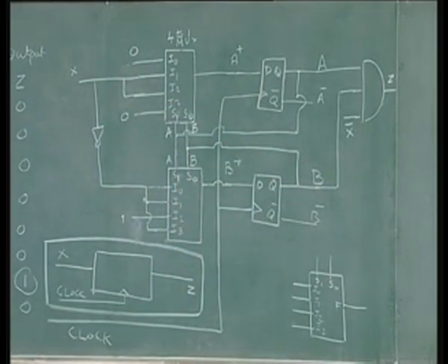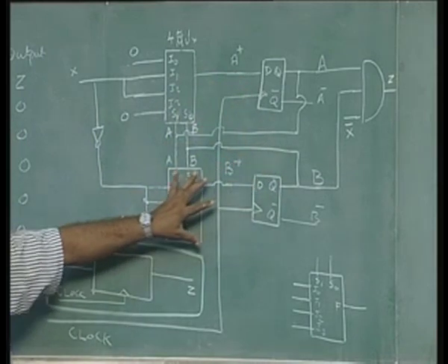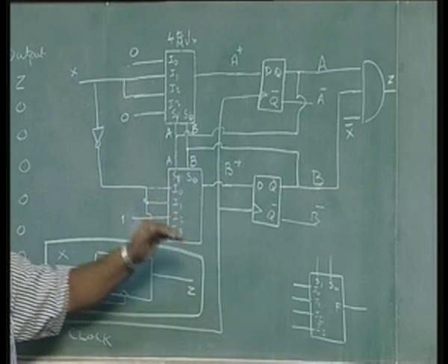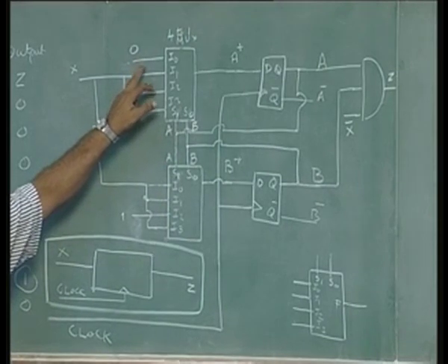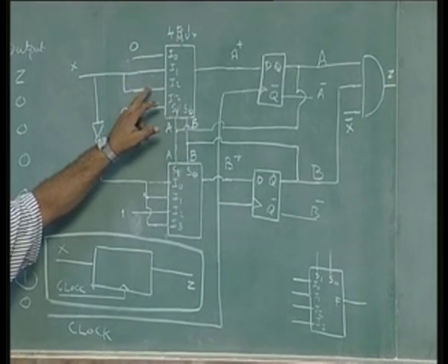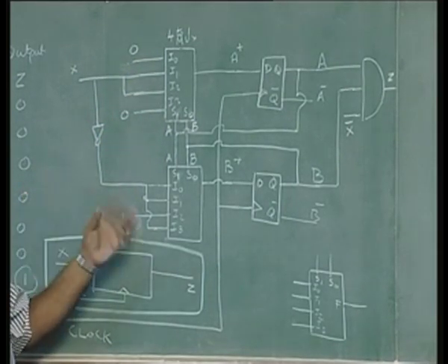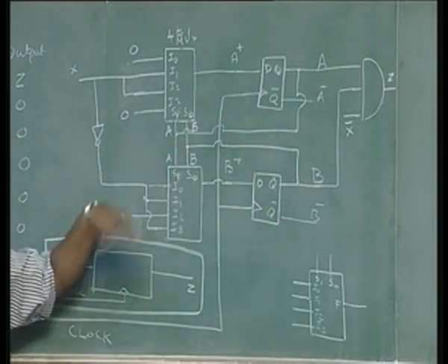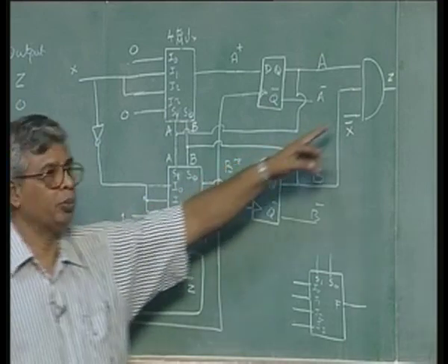This is a very simple design for two reasons. Reason 1, this part of the circuit is same. Any design up to 4 states will have the same 2 multiplexer architecture. Only the inputs to these multiplexers will be different. So, for the given architecture with 2 flip flops and 2 multiplexers, I can design any 4 state machine. Of course, the combination logic of the output also will be different.